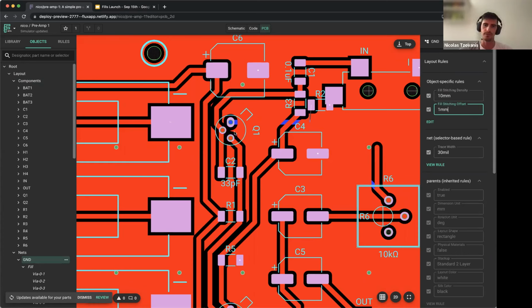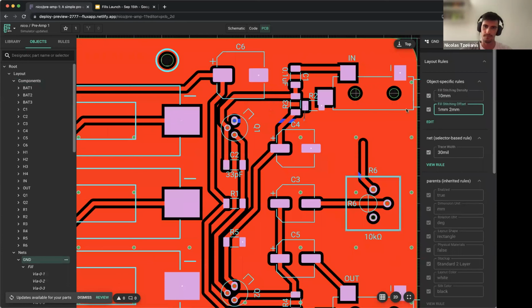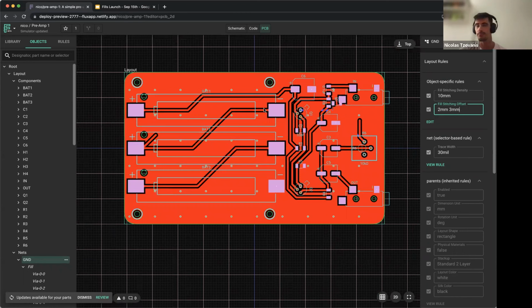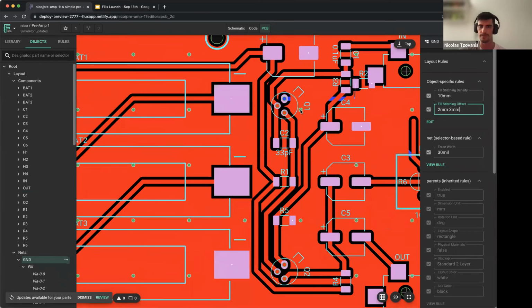Or you can modify the offset of your vias and make them land exactly where you need. In many cases, this is going to be a tricky approach. The best way is going specifically to that island and placing the via to make sure that it is connected to wherever it needs to be connected. Because in most cases, except for very specific cases, you don't want here. So when I moved the stitching via, I automatically got a via placed.